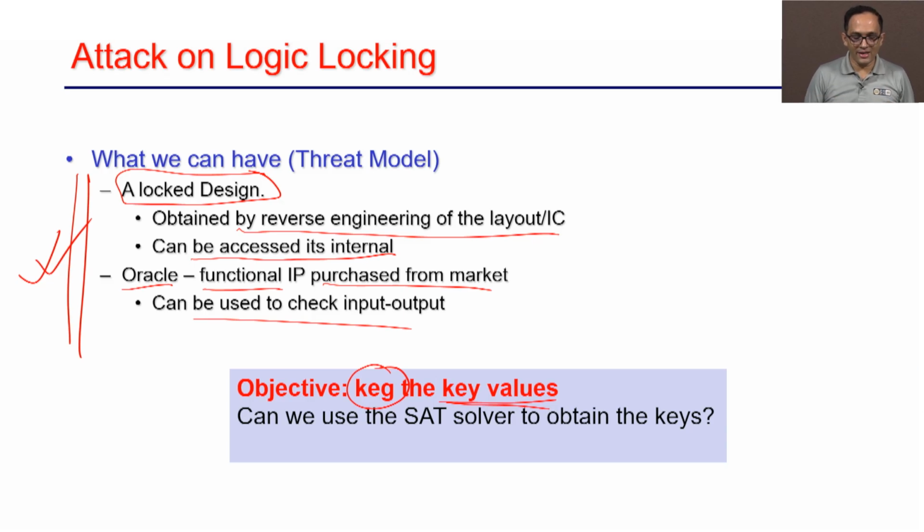Now, the question is, can I use a SAT solver to get the keys? That is where this is related to the topic I am teaching in this course, the SAT solvers. Let us understand how I can model this key identification problem as a SAT solving problem, or rather how I can use the SAT solver internally to identify the keys.